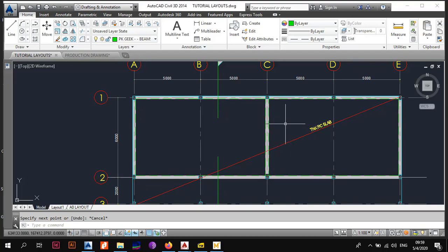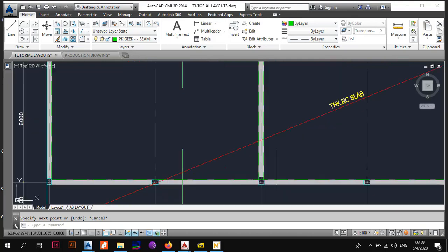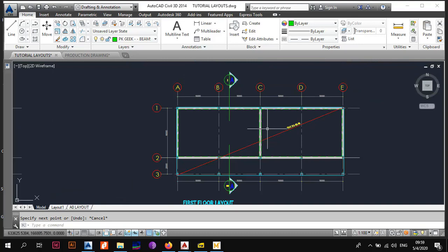So if we have our slab being supported by the wall and we remove the wall, then we're going to cause catastrophe. There's going to be a disaster. That is not going to work. But when we have a beam carrying our slab right above the wall, you can remove the wall, and your slab will still be integral. It will be supported nicely.